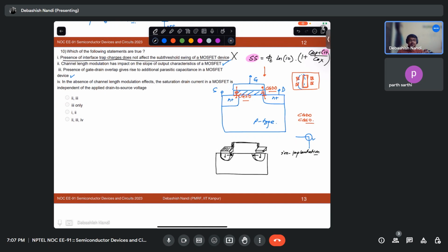I recently encountered some exotic devices where they take the substrate and dig a hole, and in that hole they put the gate material, and on top and bottom of that they put the source and drain contact. In those kinds of cases there are no overlap capacitances.